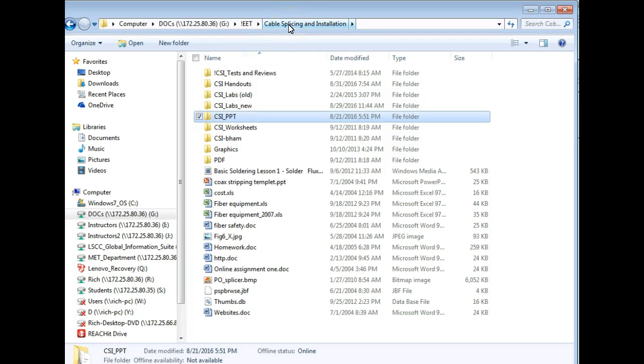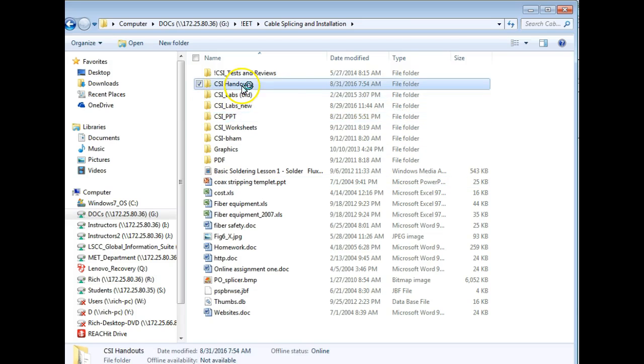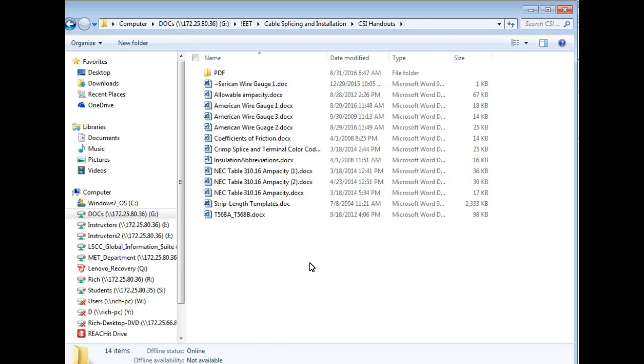T is thermoplastic. And then if it doesn't have anything out there, like TW, TW tells us that it's capable of being used in moist environments, and it's rated at 60 degrees centigrade.